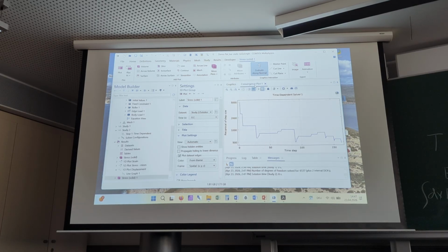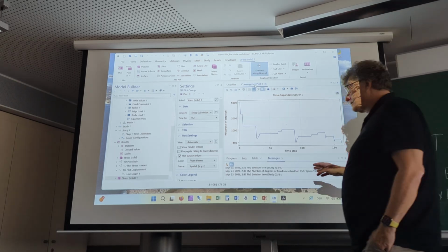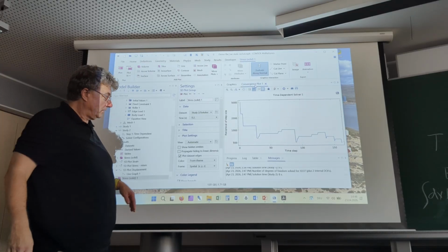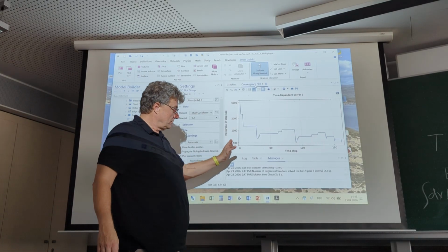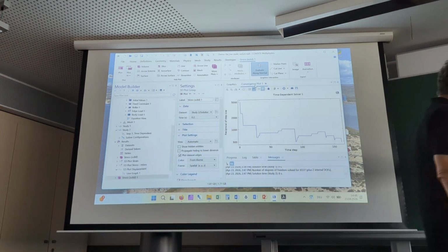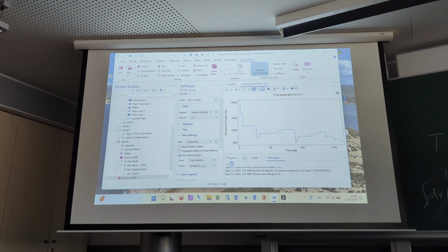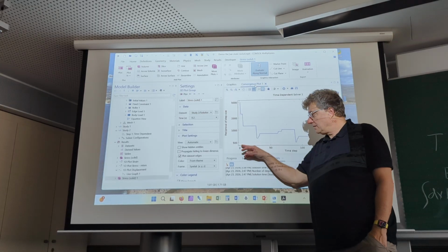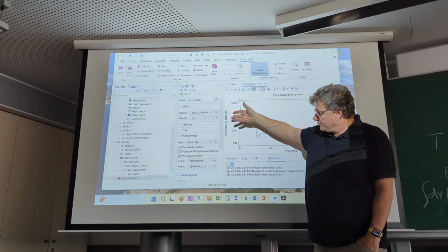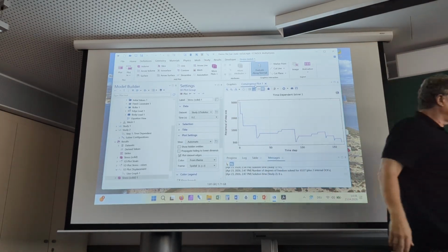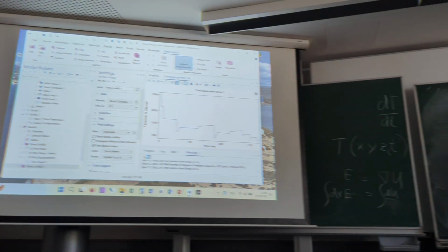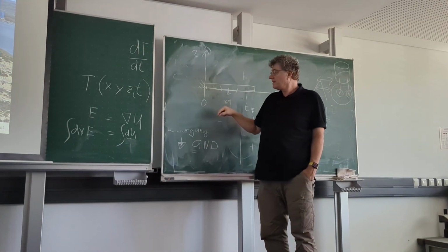A transient simulation usually takes much longer. If it takes longer, it might be interesting for you to go to the convergence plot and know how to interpret this. So it makes several simulation steps in order to simulate the specified time range. And what is typical, it starts with a large number. Actually, that number is the reciprocal of the time step. So if this is a large number, it starts from 0, and the next time it tries to simulate is very close to 0.